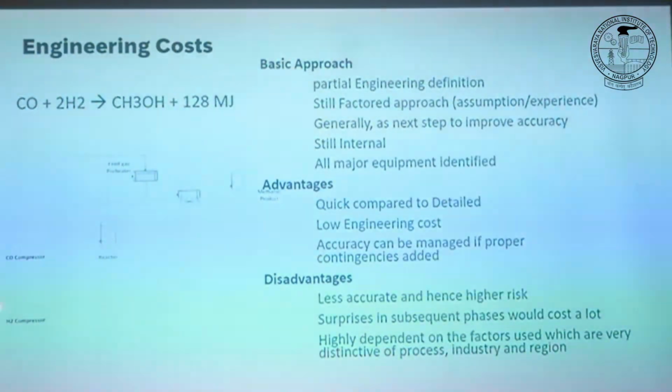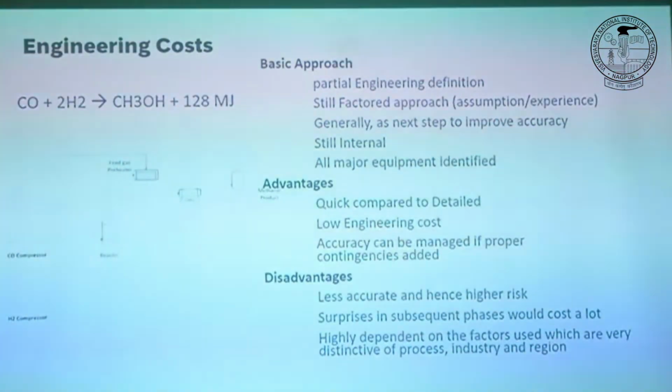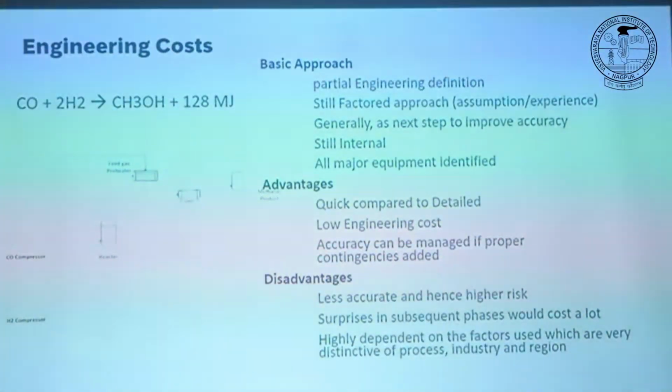You are not going to install a spare reactor, which costs 20 million, because then your plant cost will not be 37, but 57. But you can install a spare pump which costs only 1,000. Then your plant cost goes up to 37.41, but you increase the availability of the plant in case of your pump failing.